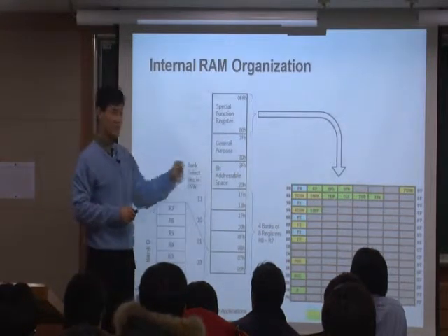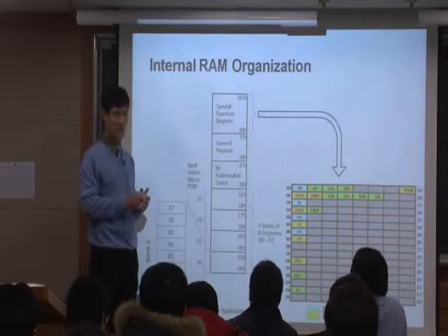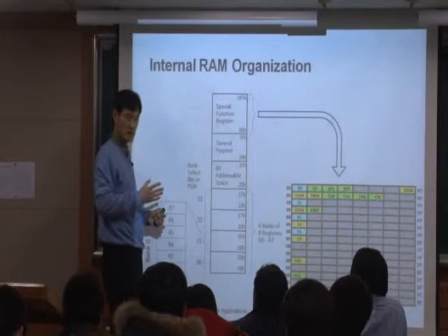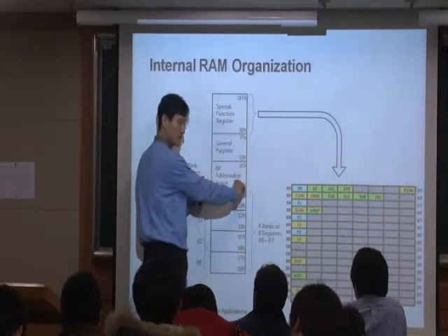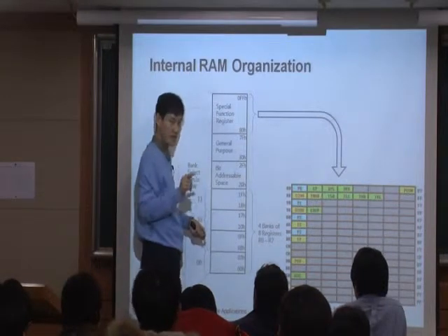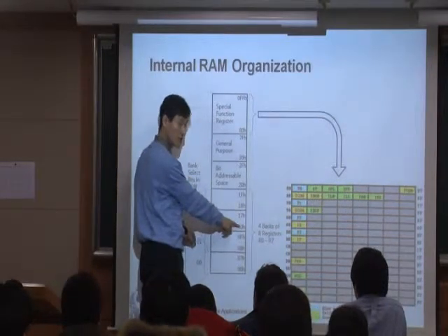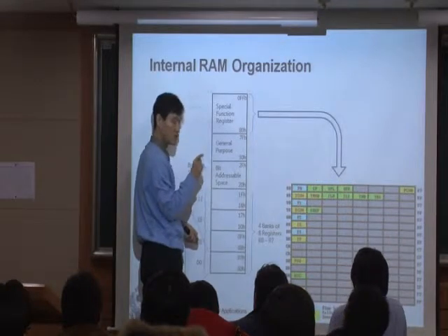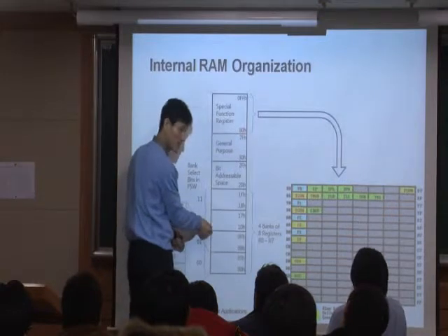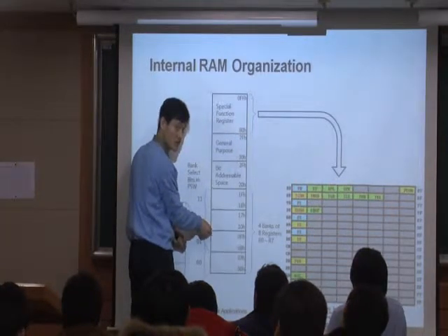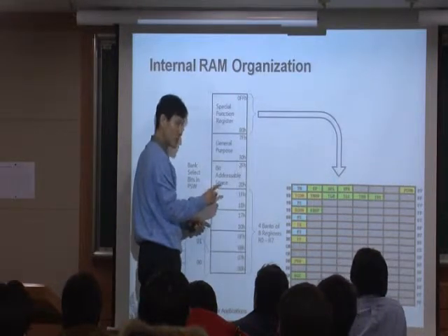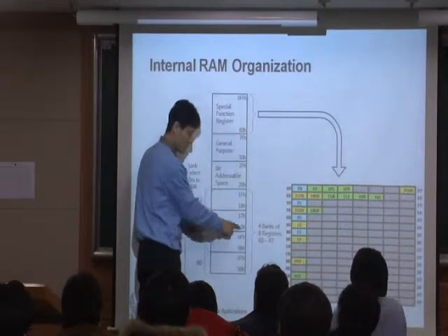You cannot do the bit addressing. Generally, in a microprocessor, bit addressing is not possible, right? You see what I'm saying? So a byte is 8 bits, right? Let's say you have address 10H. When you say address 10H, that basically means that you want this byte, 10H. You cannot say, okay, I want to access only 1 bit inside this byte.